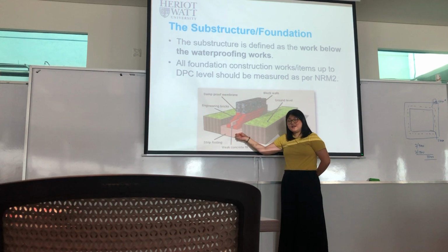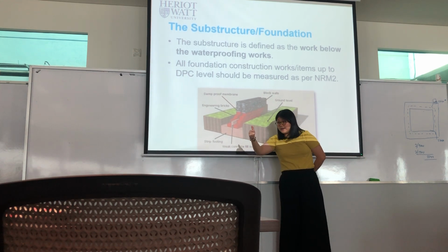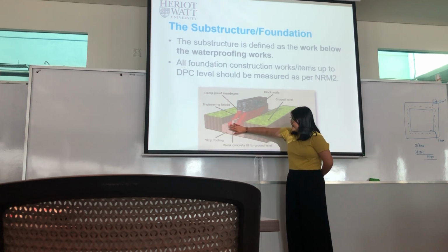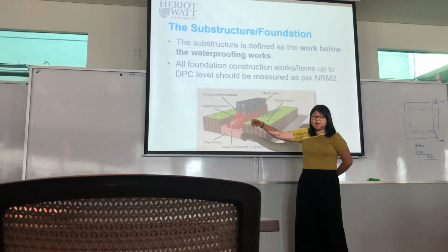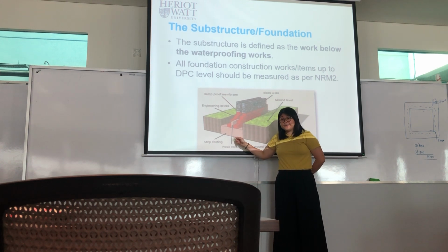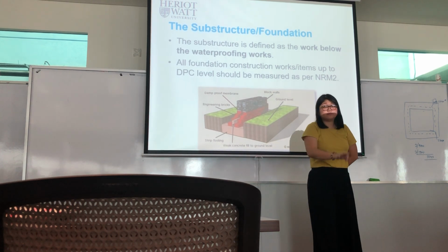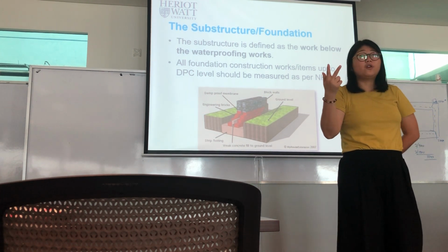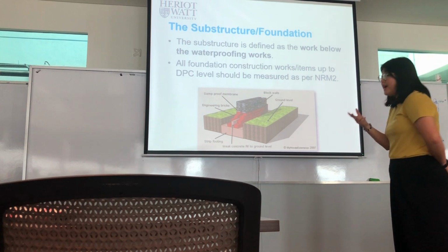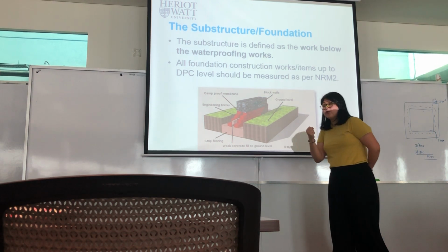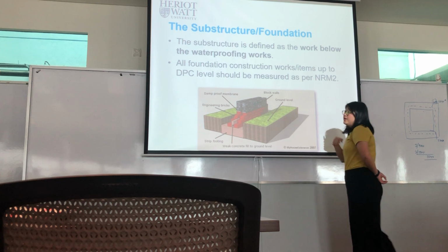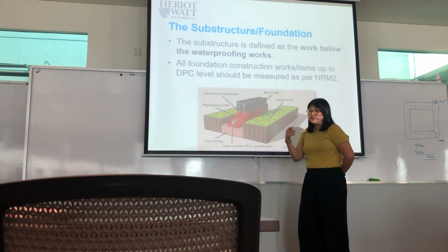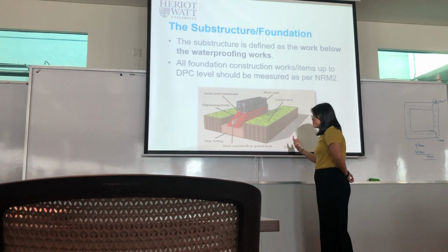Okay? Then, you start to do the concrete foundation. So concrete, what do we have? Because it's a ground floor, we might not need formwork, but at the edge, you need formwork. You pour your concrete. Reinforcement bar. When we talk about concrete, there are three items: concrete itself, formwork, and rebar. Rebar means reinforcement bar. These three items will come together when we talk about reinforced concrete. How to measure your reinforcement will be taught in the next module.